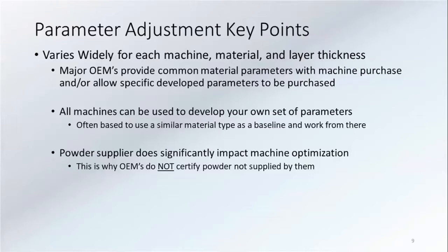A lot of that comes back to the fact that their recoater is designed to handle a certain type of thing. Their laser parameters are designed to deal with a certain type of powder. And I've taken one machine supplier's powder, for example, something like taking a Renishaw and putting it in an EOS or a 3D Systems machine, or EOS and a 3D Systems, something like that. We've done those, and they don't always work well in the other person's machine.